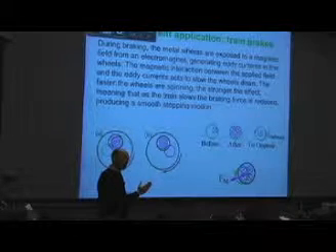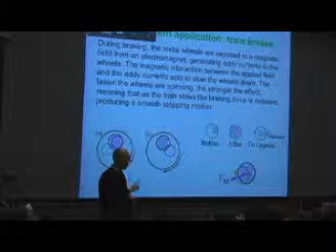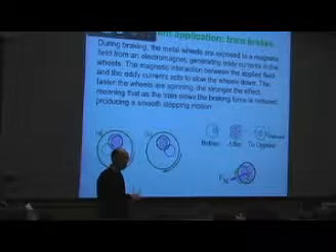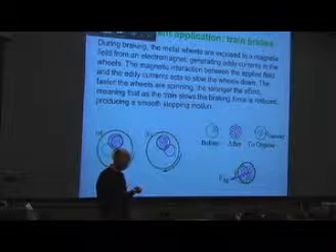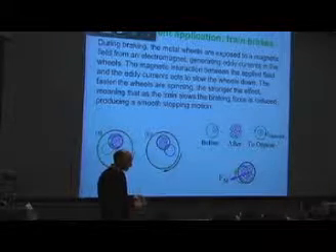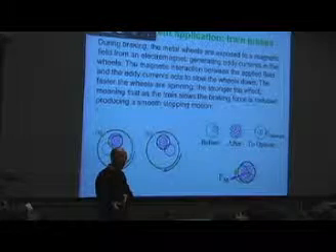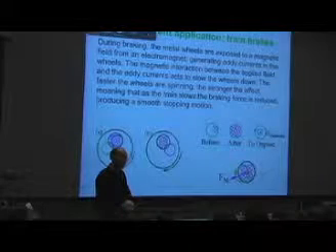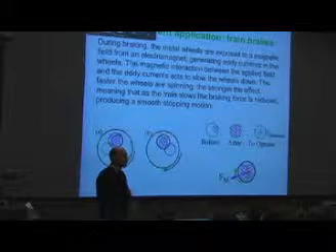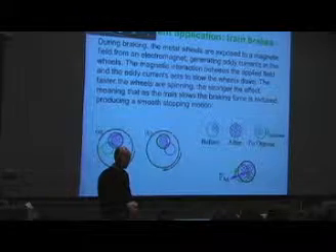Okay, so when you get your right hand going, if you only reverse one of those things, current or field, then your right hand's going to get a force that goes in the whole opposite direction as it did before. But if you reverse both of them, the field and the current, it's like taking a negative and a negative. What do you end up with? Exactly where you started. You're always going to get a force that tends to oppose whatever's producing the change in flux, and that's the motion of the wheel.